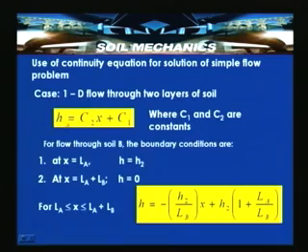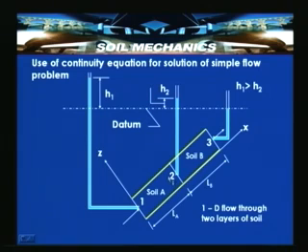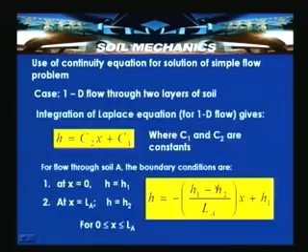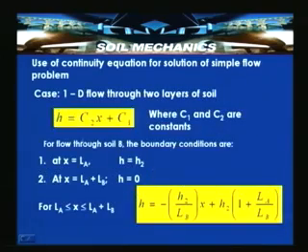Now, similarly, when we consider the flow taking place from point 2 to 3, that is in the region of soil B. In the previous slide we showed a figure having 2 points, 2 and 3, which is shown again here. This is soil B, with flow taking place between 2 and 3, that is length LB. Let us now consider the boundary conditions. Again the flow is taking place in one dimensional direction, so del square H by dou x square is equal to 0, and integrating we get H is equal to C2x plus C1.